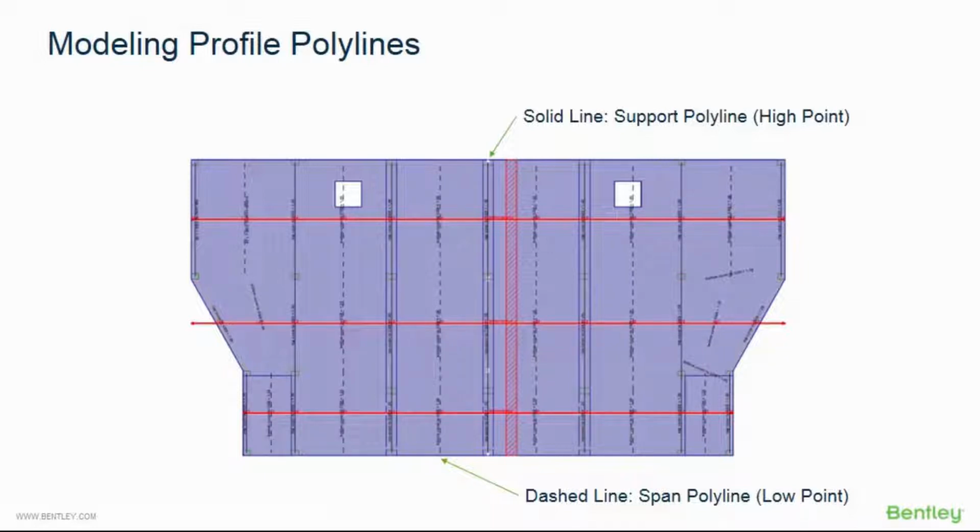Profiles for distributed and banded tendons are determined by creating profile polylines on the tendon parameters layer. Tendon half spans are created wherever a generated tendon intersects a profile polyline.